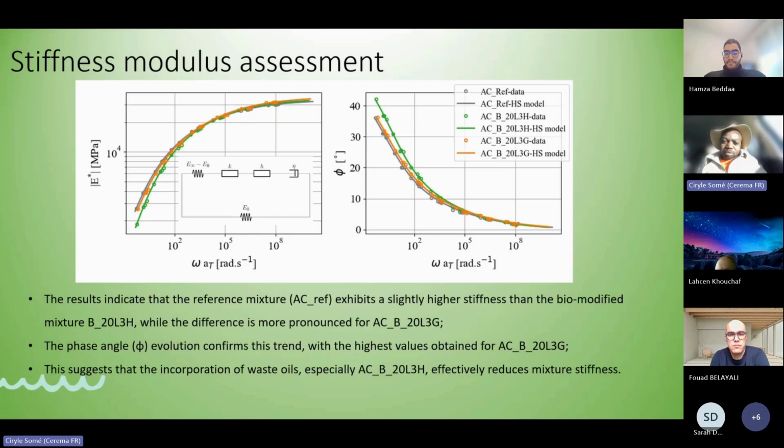It was also possible to present the results as what we call isothermals, which is the stiffness at each temperature. But this representation, which we technically call a master curve, allows us to have a big picture of how the stiffness increases and decreases depending on the temperature.